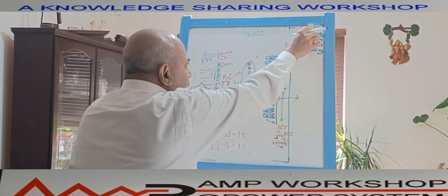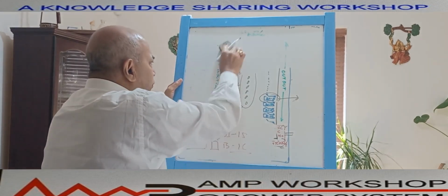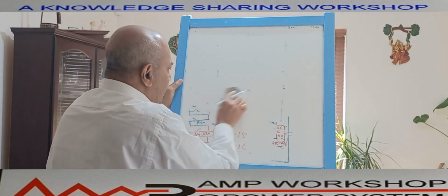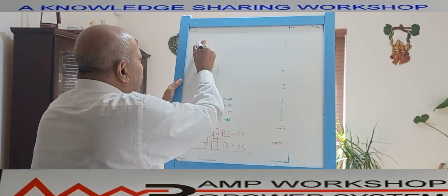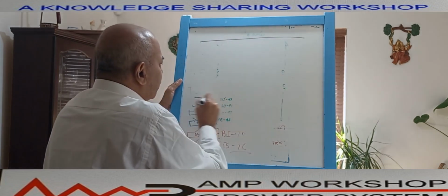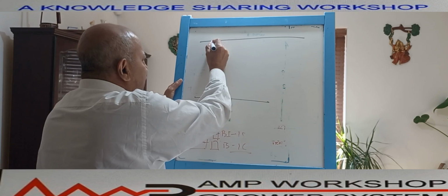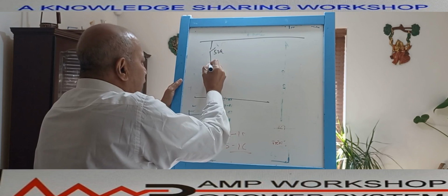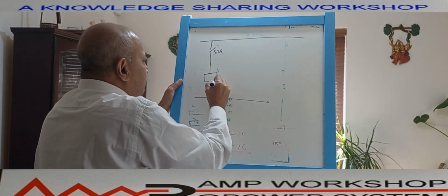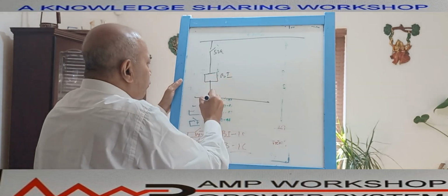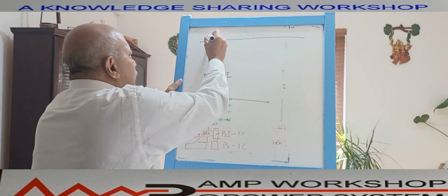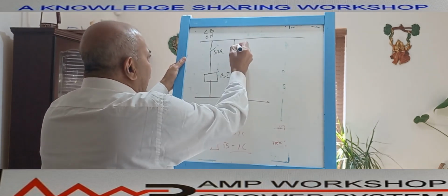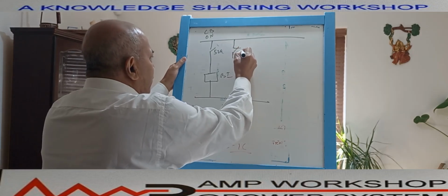How will it actually look in the schematics? We can draw some drawing for that. Suppose this is a 24 volt DC. Now suppose I am giving breaker 1 status. How will I give it? This is a breaker 52A contact. It will connect to binary input 1. This is breaker 1, the CB1 status. It will give the CB1 status.